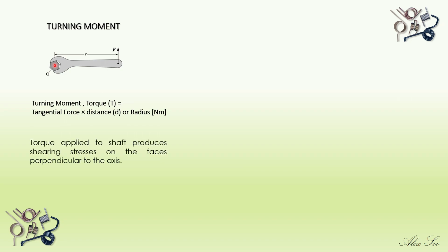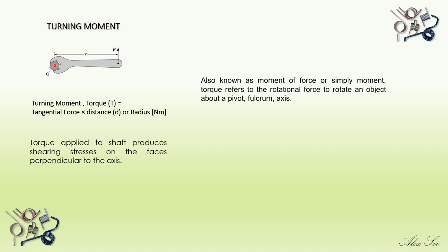Torque applied to a shaft produces shearing stresses on the faces perpendicular to the axis. Remember, shearing force and area must be parallel to each other. Torque is also known as moment of force, or simply moment.